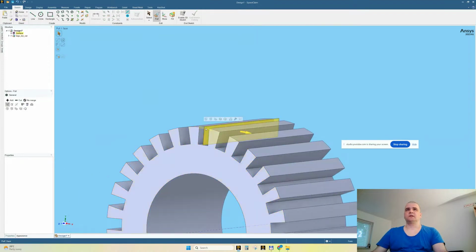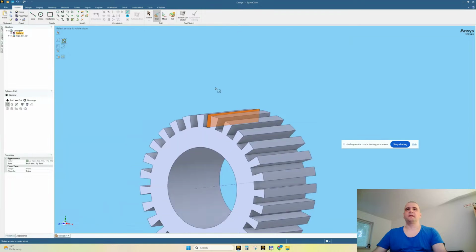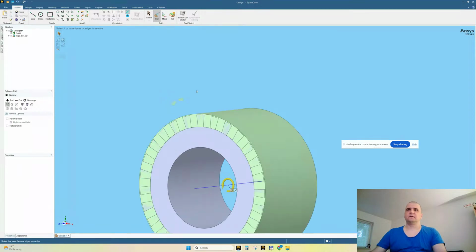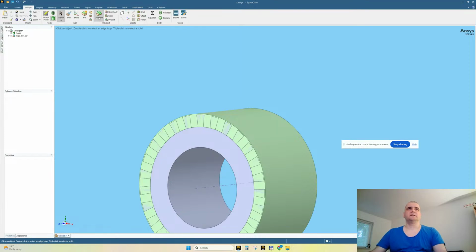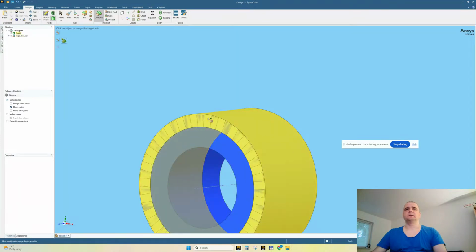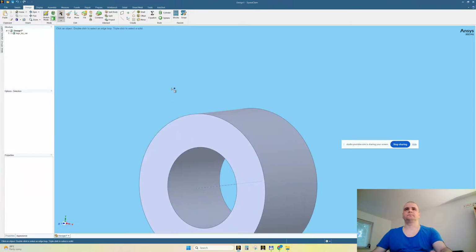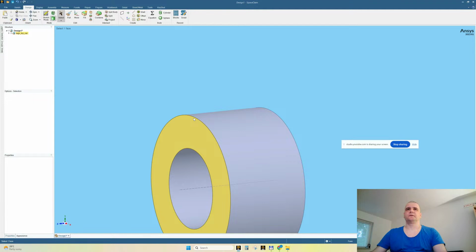And this, I will click on this. We have revolve, and I'm clicking on the axis. And I will write from the keyboard 360, all right? It is an additional body. So now we can go with design combine, and this is what I have.